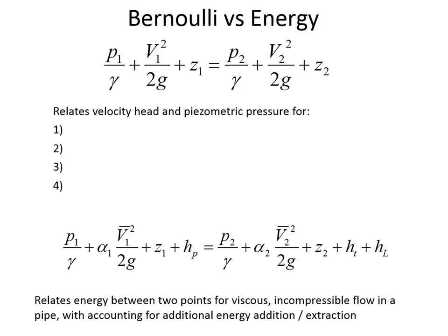That spinning impeller is connected to a generator, which is just like an electrical motor in reverse, and the generator sends electricity out. And so T is turbine, and it's intentionally on the right-hand side of the equation because between 1 and 2, what we're saying is that there's a turbine somewhere between 1 and 2, and that turbine is taking energy out.